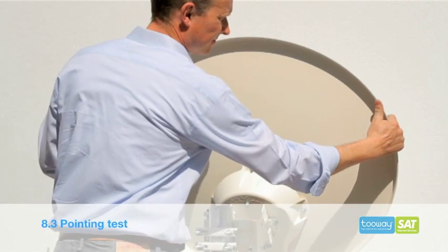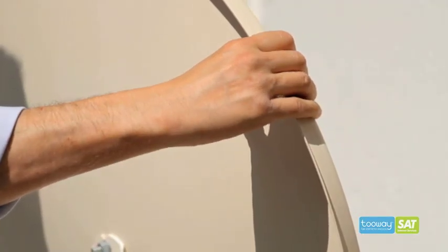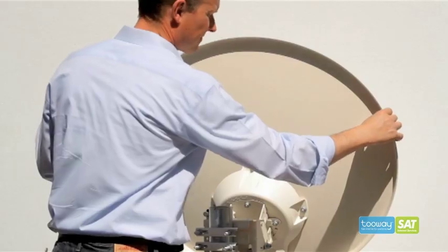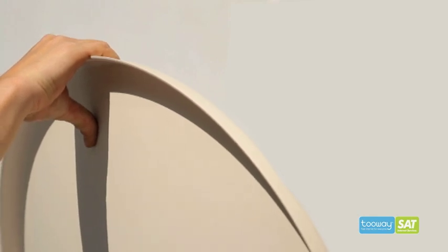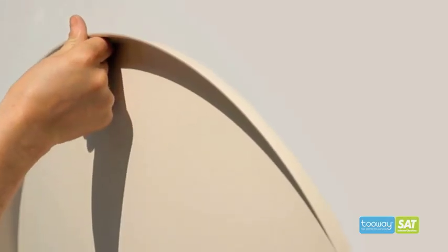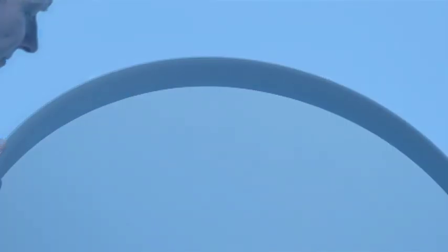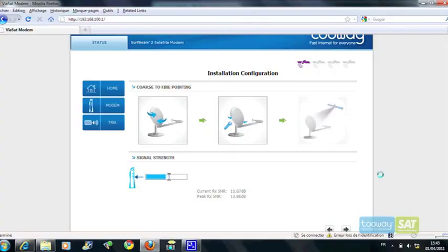To test if the antenna is correctly pointed, you should now perform the pointing test. Carefully, without deforming the antenna, pull and push on the left, right, and top outer edges. When you release the antenna, it should go back to the continuous tone. Once the pointing test is finished, you'll see a third box with a tick. Once you have a tick, you click on the arrow on the right-hand side.